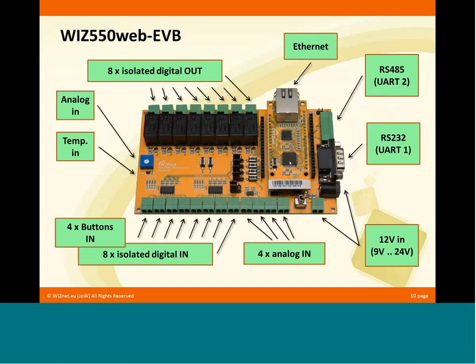And here you have the MCU with the crystal for the MCU to have it clock synchronous on the UARTs. Such MCUs provide also internal clock references, but with the crystal you have the best performance on the UARTs.